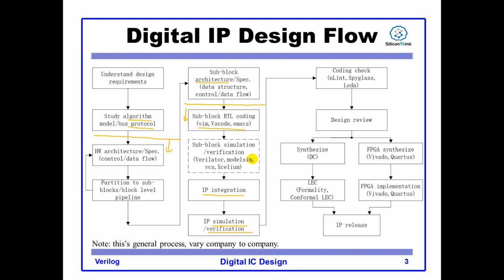using this environment. For example, it may be something like this. This is your design, that is the design under test. Then you will write some blocks to generate stimulus to it, that is, drive the input signal of your design.